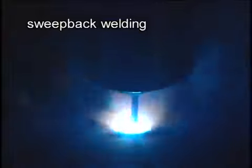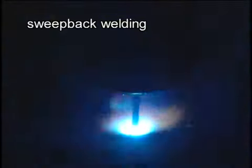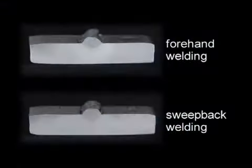The sweep-back welding method is used for special cases such as deep beveled welding that is able to handle this type of bead shape. Opposite characteristics are shown in the weld macro section when forward welding method and sweep-back welding method are compared. Observe the differences in penetration, bead width, and weld reinforcement.